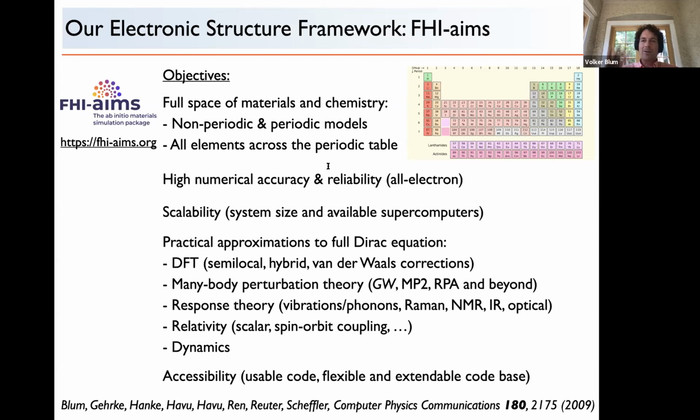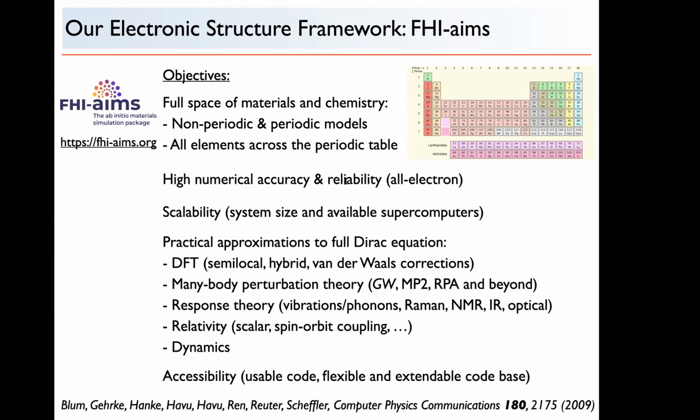And I do have one more. Sorry that it's all answered in the chat, but hopefully that's okay. Why are numeric atom-centered orbitals obtained by fitting to data obtained from dimers specific? It's a good question. So they don't have to be done that way. You could create your own. You can also use Gaussian type orbital basis sets in FHI-aims. That's possible, although we didn't optimize the species defaults for those heavily. We use them mainly for reference purposes, but you can optimize and they work quite well. You can use Slater type orbitals. They exist and you can implement your favorite by creating an input file, your favorite Slater type orbital basis set. So we don't need to fit to dimers.